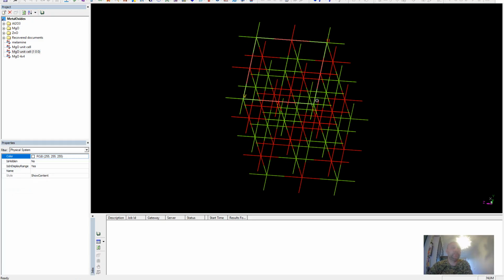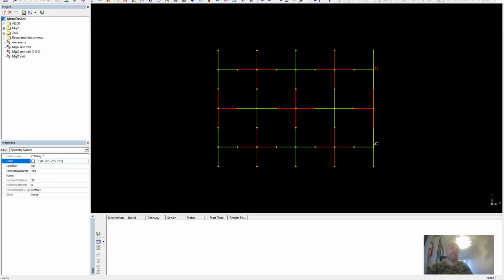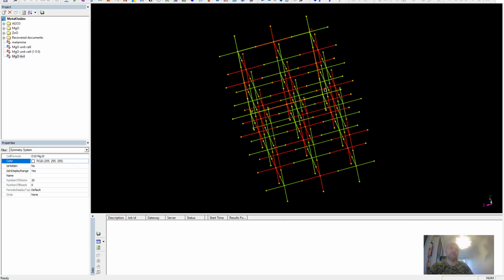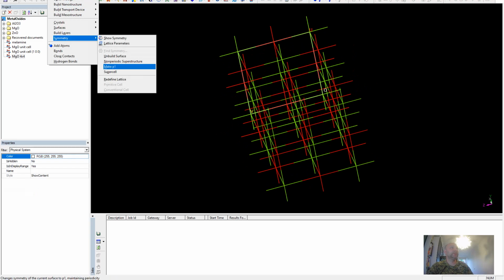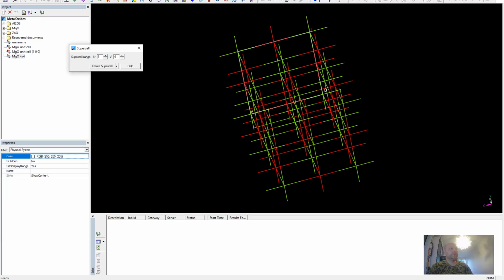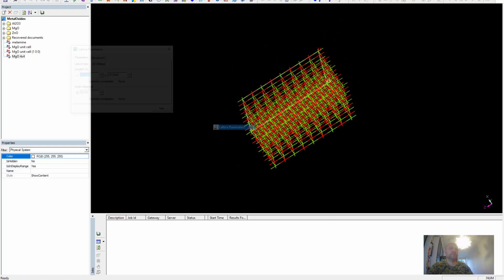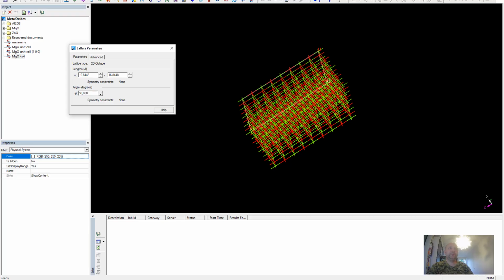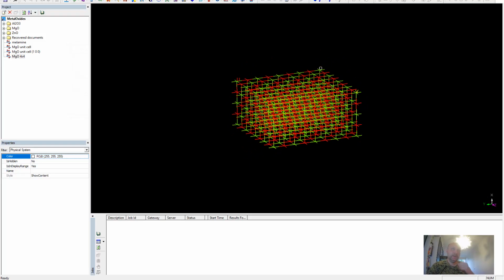Okay, so let's copy it. I'm going back to the original document. I press Ctrl C to copy the whole system, I go to the new MgO document, I press Ctrl V, and I copy my structure. Now the supercell. I go to Build, Symmetry, Supercell, and I choose 4 times 4. And that's my system. I can check the lengths. Okay, everything looks good. That's my system, which is ready to proceed with the publication.